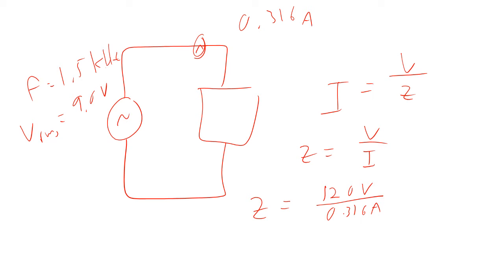And so that turns out to be equal to 28.5 ohms. Okay, so, well, that's not the same as you got before, because before you got 15.6 ohms. So you know from before the resistance is going to be 15.6 ohms, but the impedance is 28.5 ohms. So what that tells you is there's got to be something other than resistors in there.